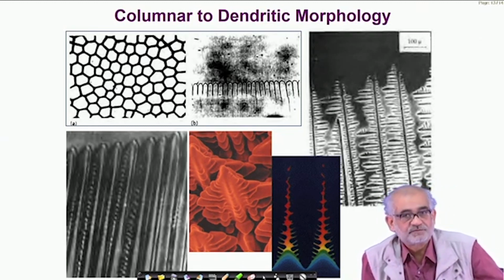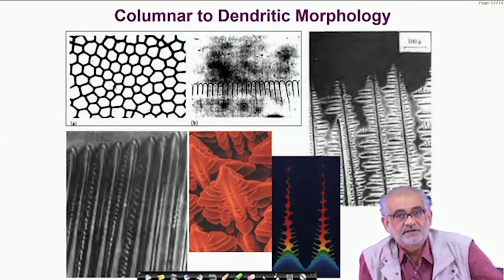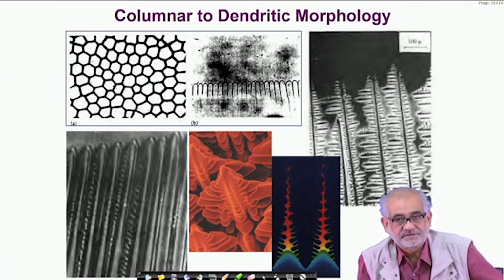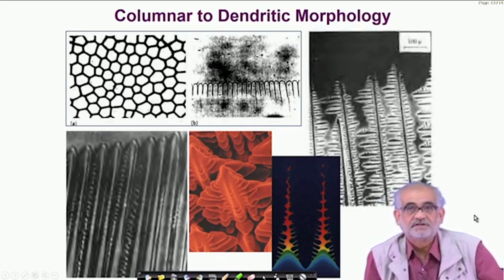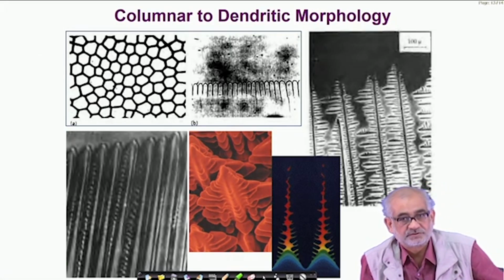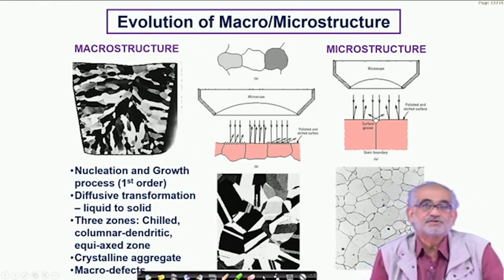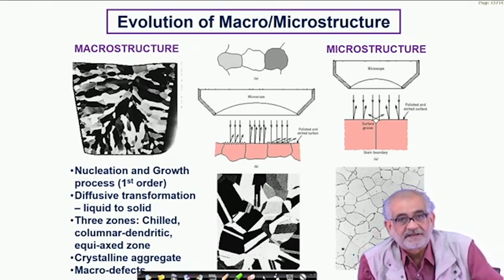Suffice it to know that when we form solids, essentially which will be useful to us, and in this particular course where we want to deal with the surfaces of those solids, we have to realize that whenever we form solids either directly from the casts, from the melting-to-casting procedure, then we may see such macro or microstructures developed in the bulk, in the core, and certainly also onto the surface. Similar structures one may see also happening when solid is formed directly by condensation of a vapor. So this leads to the concept called microstructure.